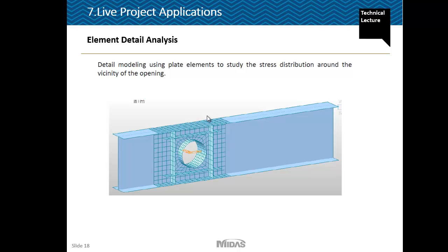For example, it is common in steel girders that you have holes in the web, basically for service accessibility reasons. You can give scale factors to the web to consider the reduction in stiffness property, and for analysis purposes to consider the stress distribution accordingly.